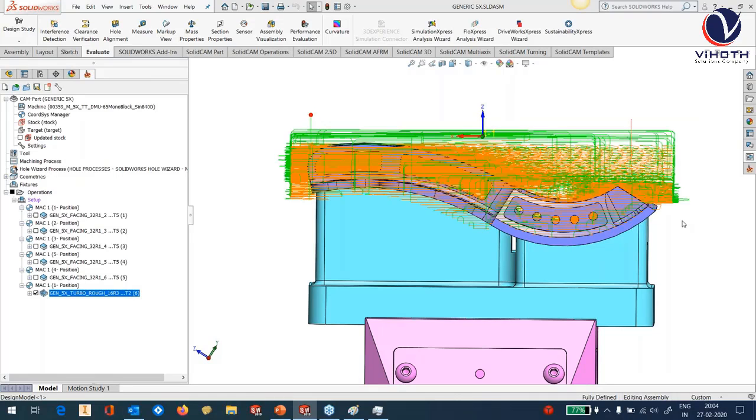You can see the result now. It understands that the stock did have undercuts and it was only doing air machining otherwise. So now it has taken the shape of the stock and also stopped the toolpath accordingly. Very important feature because you could be spending at least 15-20% more time just cutting air and doing nothing else.